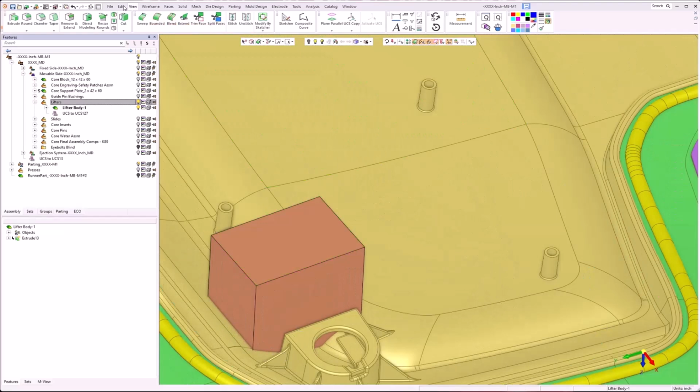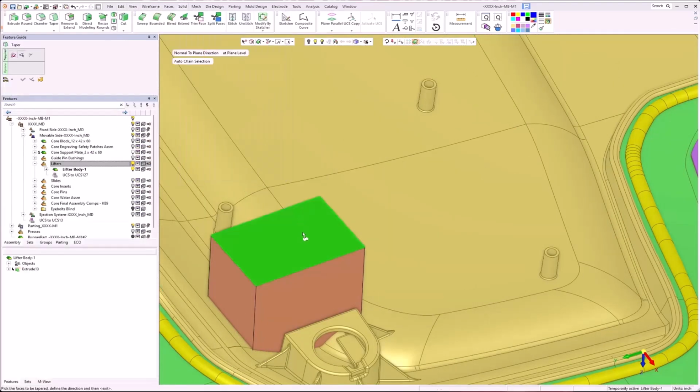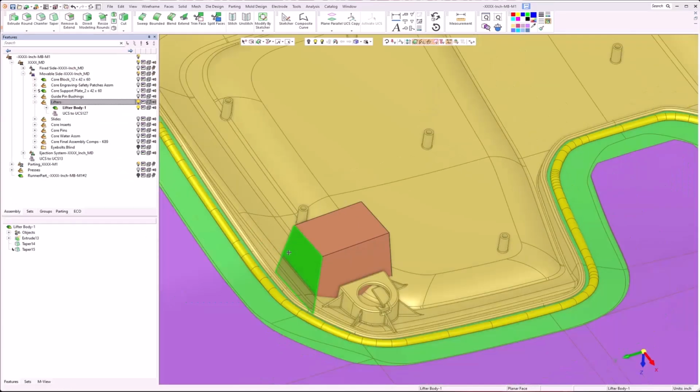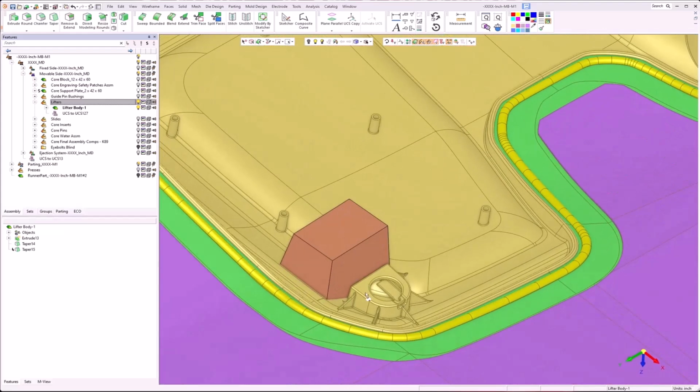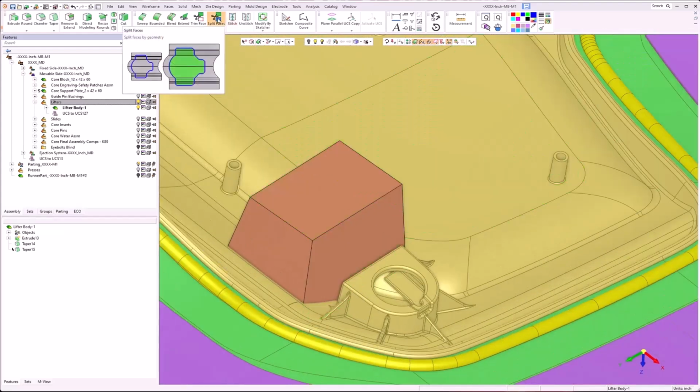I'm going to add taper. And taper. Later on, at the back angle, when I add my lifter rod and I calculate how much travel on that, I'll be able to update it or tie it to the lifter rod, and it'll update automatically and keep it pretty clean going forward.